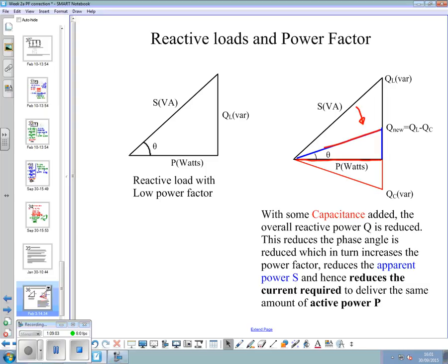What they don't do is try to get it completely in line. They don't go for a cos theta of 1. Not fully sure exactly why, but there's a danger in going right on that line where your capacitive and inductive reactance are equal to each other. It's not a good idea in high power systems. All right.